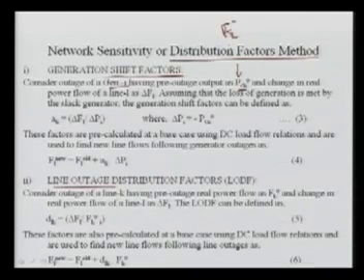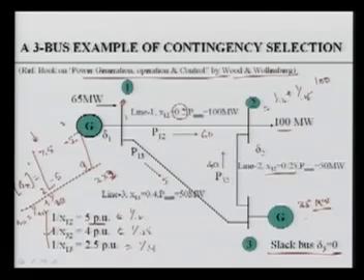To see this, what will happen, I will just explain to you. If we take this example, let's suppose this generator is in outage. This generator is tripped. What will happen? If the load is constant, then instead of this one, this generator will be generating 100 megawatt. And if it is generating 100 megawatt, the power in this will be rerouted. Power will be totally different.